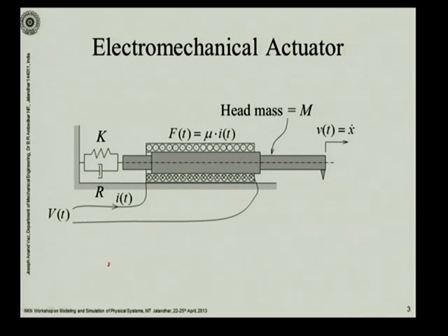You can consider a one junction where you have the winding current, and here you can take the voltage that is being applied on it, and here you can assign the inductance using an I element, and also you could assign an R for the winding resistance.